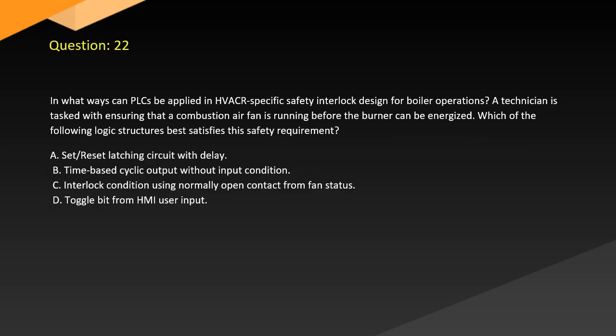Question 22. In what ways can PLCs be applied in HVACR-specific safety interlock design for boiler operations? The technician is tasked with ensuring that a combustion air fan is running before the burner can be energized. Which of the following logic structures best satisfies this safety requirement?